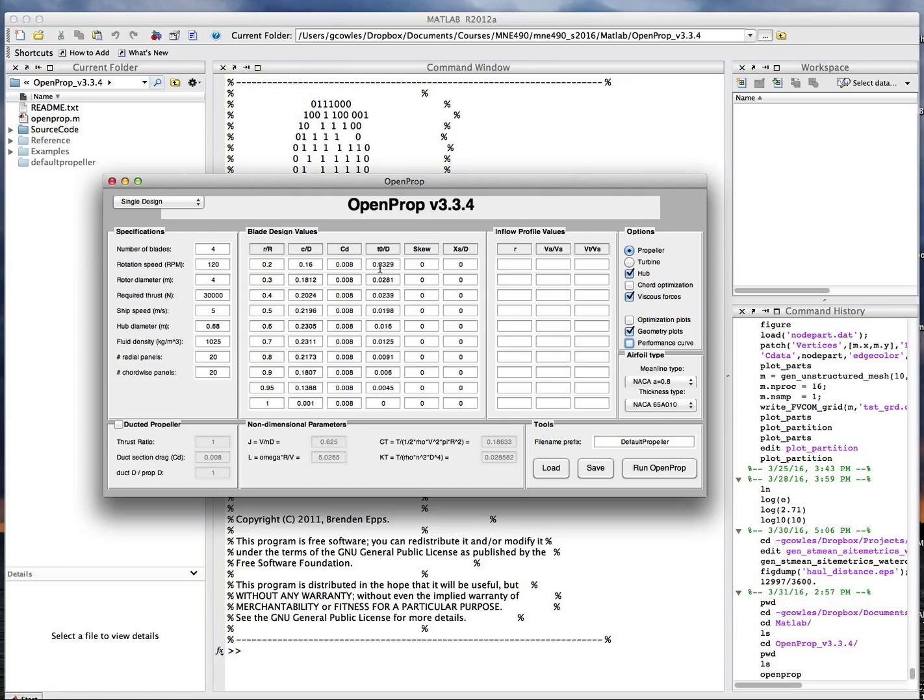And so that basically sets up the geometry except for twist, except for the pitch variation of the individual components. And what the program will do is pitch the blade until it reaches a pitch angle at which it can produce this thrust coefficient, which is 0.028. That seems very small. I must have missed a 0. Hang on. Okay, that's better. 0.28 at an advance ratio of 0.625.